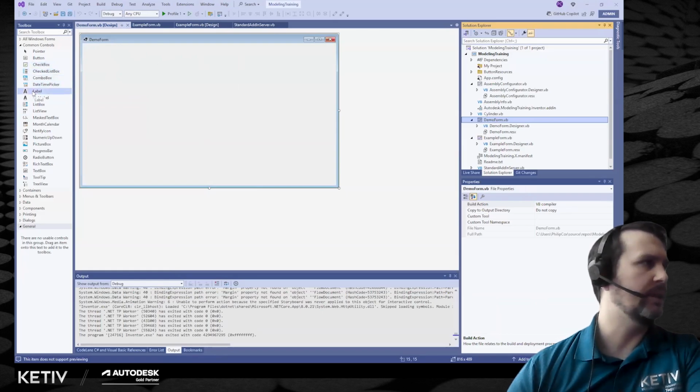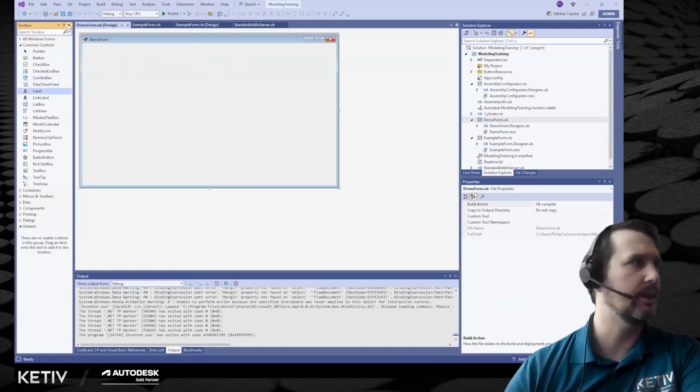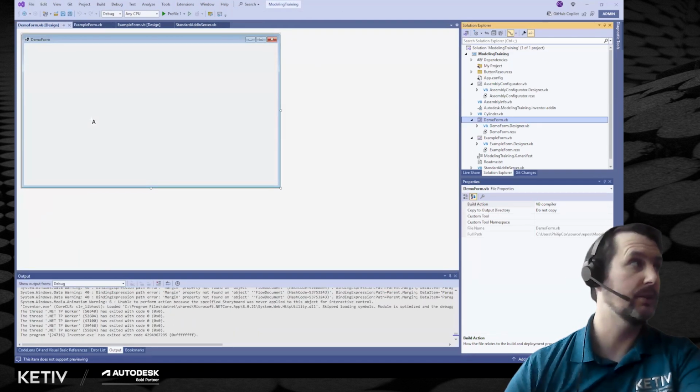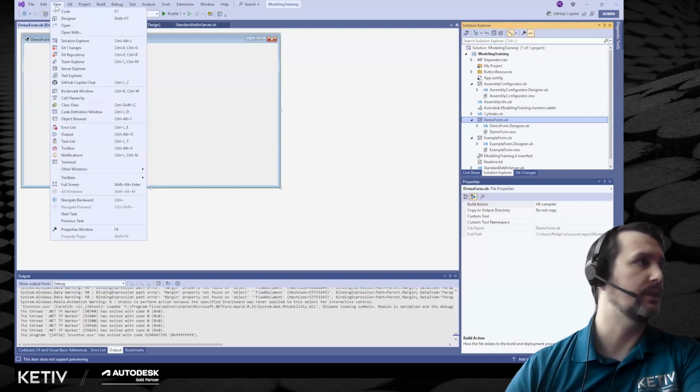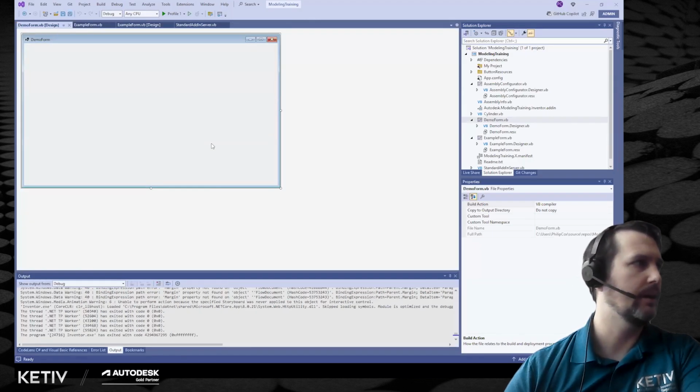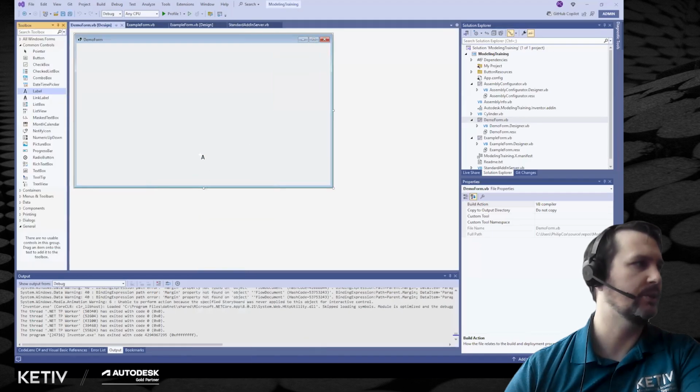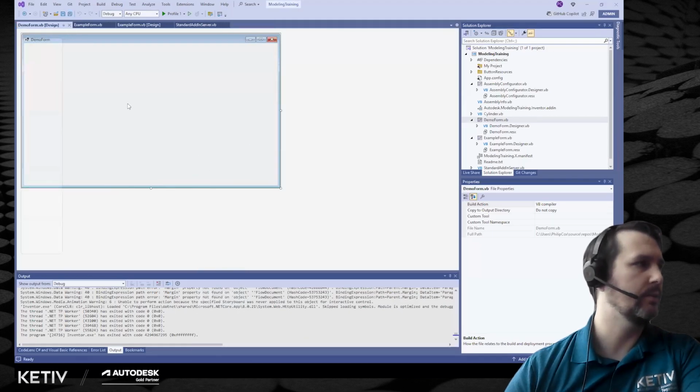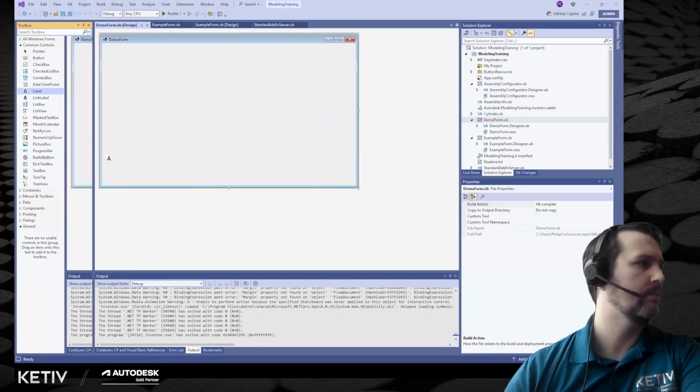So we can come in here and there's a toolbox. Now let's say you don't have that toolbox. You don't know where it is. So I'm going to just exit out of that, and you're looking at it like this. You can go find the toolboxes and different things. You come to View and hit Toolbox. You'll notice it also gives you the hotkey Control-Alt-X, and that will come here. You can pin it or make it auto hide, stuff like that. You can actually drag these things around if you like. I generally like my toolbox right over there, so I'll just leave it there. Go grab it, see if I can get it where I want it there. Yeah, there we go.